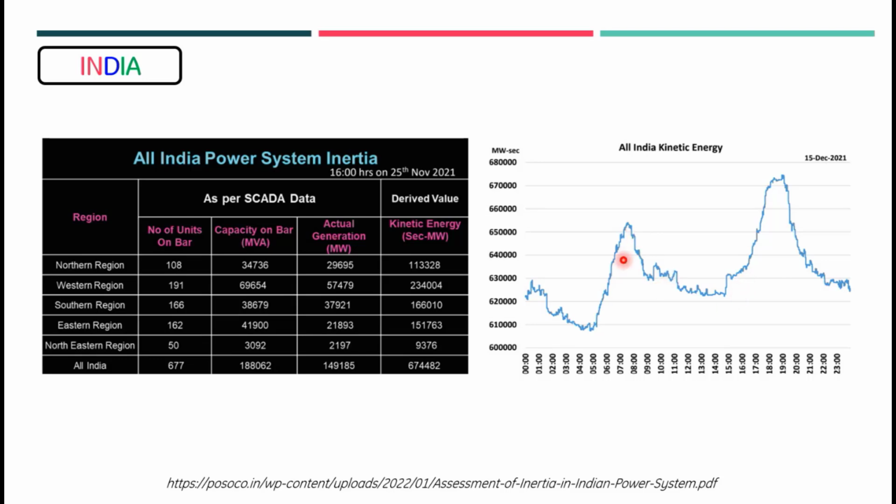So on those kinds of days, where our inertia is less, the evening peak hour comes. We bring more hydro units into service to meet this peak demand. At that period of time, we have higher inertia, and then a gradual reduction. Let us say I have set a minimum kinetic energy level. If this is being breached, I need to put additional generation resources into the system or change my unit commitment strategy so that I do not breach the minimum inertia level.